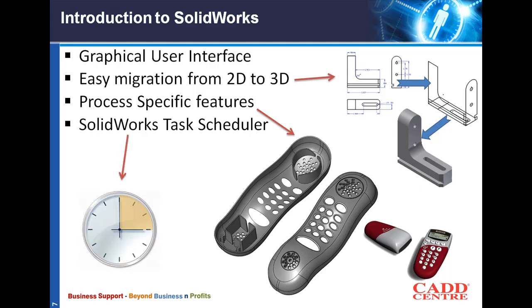The next one is SolidWorks Task Scheduler. The biggest advantage with the SolidWorks Task Scheduler is, now there is a situation. You have a task of updating all the part files which were done in SolidWorks 2008, and you want to convert these 2008 files into 2010 files. Now the typical situation, what you will do is open the files one by one and convert or save them. But using SolidWorks Task Scheduler, you can do it as simply as possible.